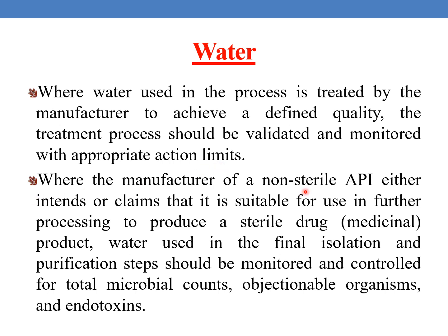When the manufacturer of a non-sterile API either intends or claims that it is suitable for use in further processing to produce a sterile drug, water used in the final isolation and purification steps should be monitored and controlled for total microbial counts, objectionable organisms and endotoxins.